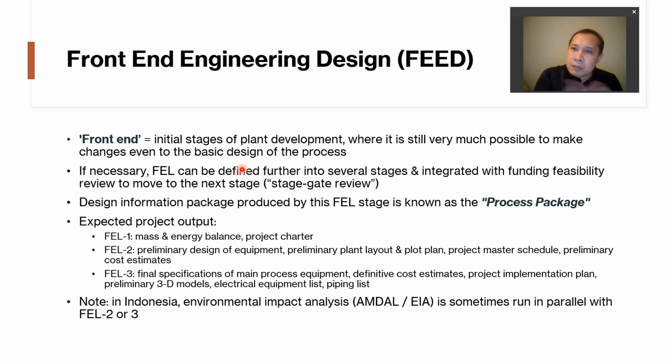Again, as I told you just a few minutes ago, whenever we move from one design stage or one project stage to the next one, there has to be what is called a stage gate review. There has to be a review done properly to decide whether we should move forward or not. The design information package produced by FEL is known as the process package. Okay. Briefly speaking, a process package is a process design that does not contain any location-specific details.